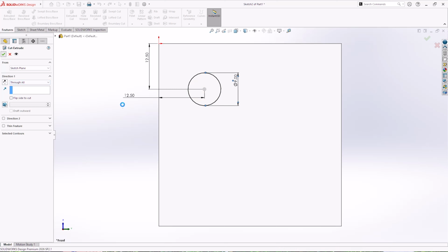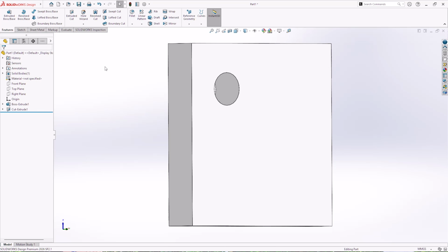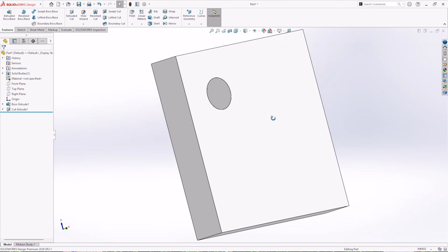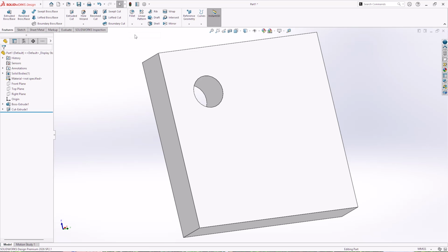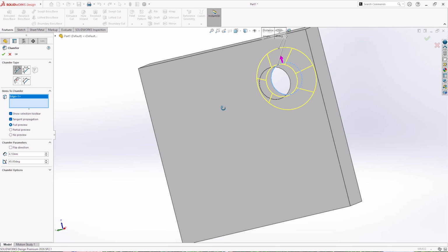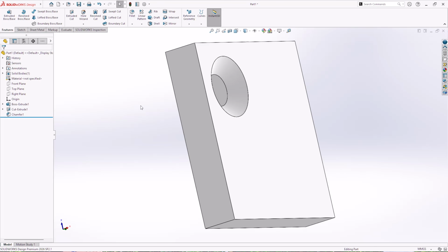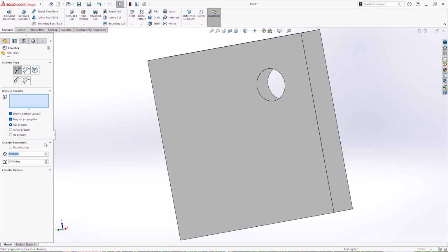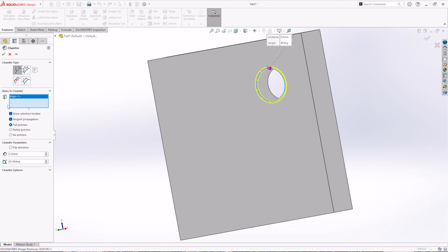At this point, we have a simple hole, but we're missing the countersink, so we have to create it manually using a chamfer feature. I'll enter 4.1 mm, which gives us approximately 17.2 mm at the top, matching the ISO dimension for the M8 flathead screw. Finally, I'll add a small 0.5 mm chamfer to the opposite side, just to remove the sharp edge. And that's it, the hole is finished.